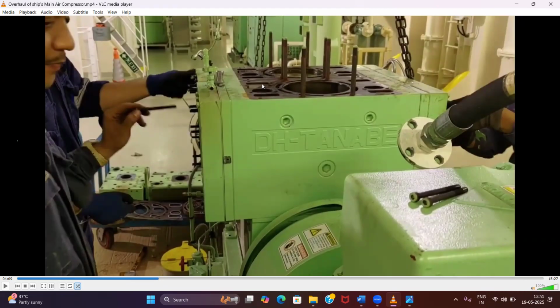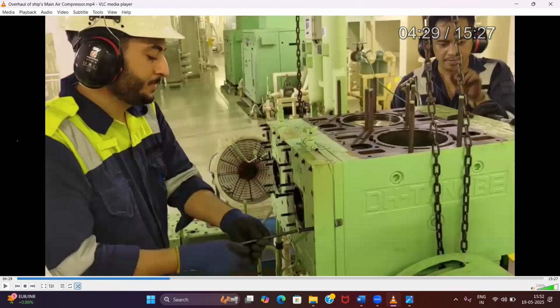And if your gasket leaks or your gasket is damaged, the cylinder head gasket which is going to come over here, can my air find its path to your water side? Yes, sir. Do you understand who asked the question? You can see clearly a lot of passages here, a lot of grooves.